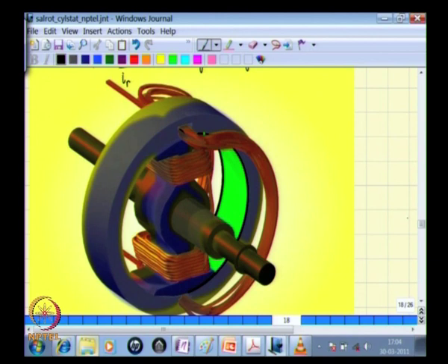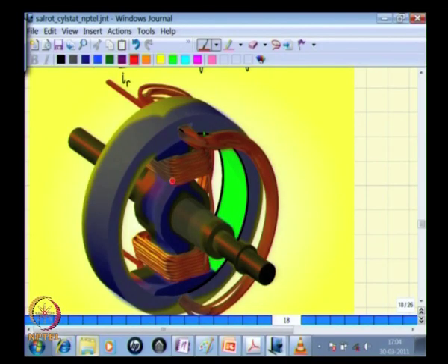So, what we have here is we are now saying that the rotor coil has been excited as before, of course, and then the flux is flowing through, but what we want to determine is the flux linkage through the rotor itself, flux linkage in this coil and this coil. The flux passing through this coil is therefore independent of the rotor angle. If you remember, we said that this flux distribution rotates along with the rotor, and therefore irrespective of where the rotor is, the flux passing through this will always be the same.